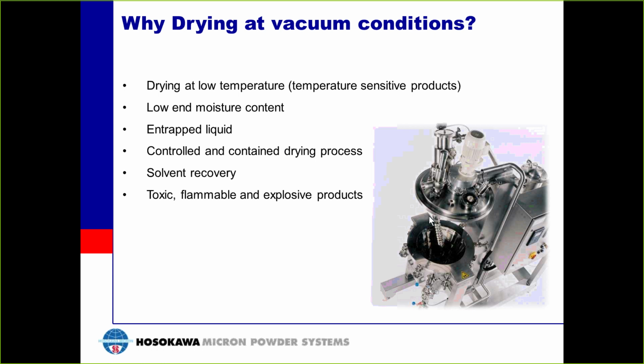It's also good because it can obtain a low moisture content, and it's good for getting out entrapped liquid. It's a batch process, and you can take the time to really dry that product out if need be. So it's good for those items. It's a controlled and contained process, and this hits on those last two points too. It's going to allow you to do solvent recovery, and it's also going to allow you to contain and control your process for toxic, flammable, or explosive products.